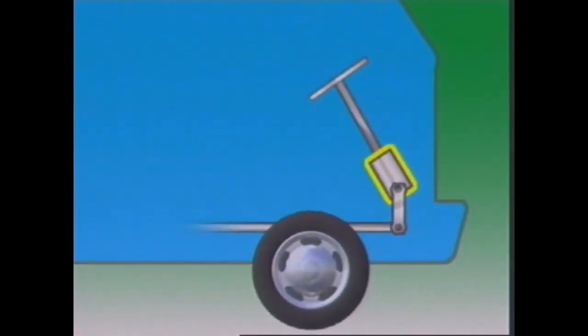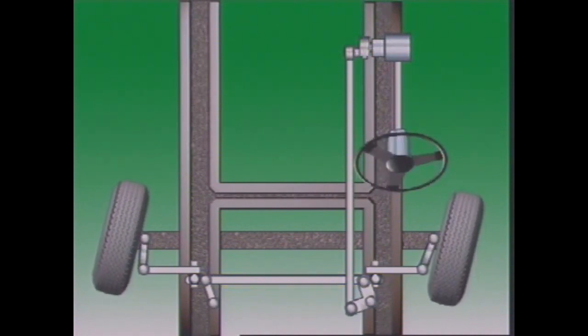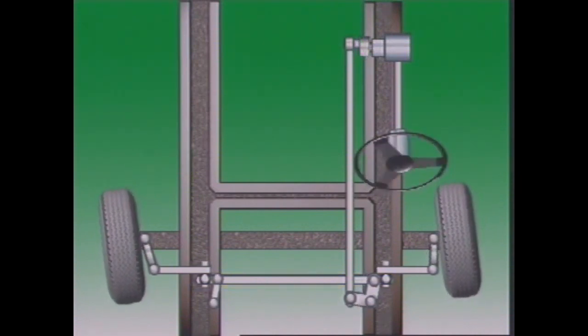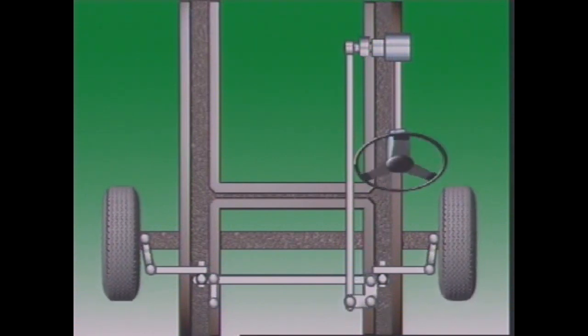In forward control vehicles, the steering system is mounted in front of the engine and wheels. The steering box is mounted on the subframe with the pitman arm vertical. A drag link transfers movement of the pitman arm to a relay lever which has two arms, one connected to the drag link and the other to the idler by the track rod. The longitudinal movement of the drag link pivots the relay lever. This transfers the motion through the track rod to the idler arm and through the tie rods to the wheels.